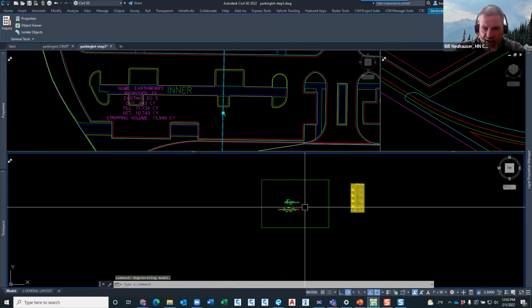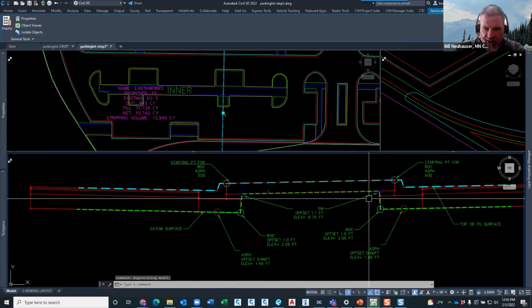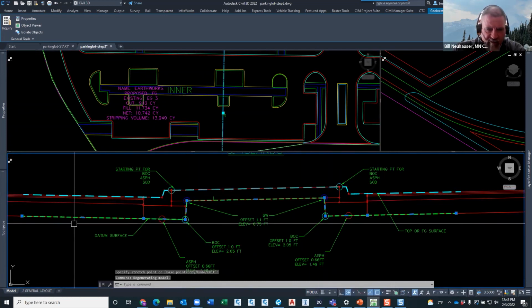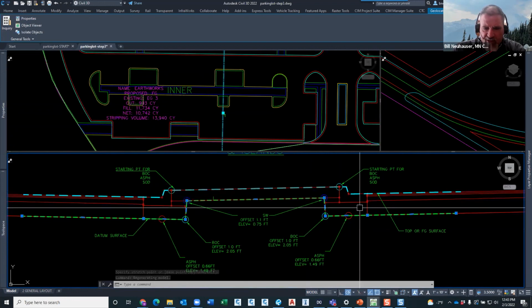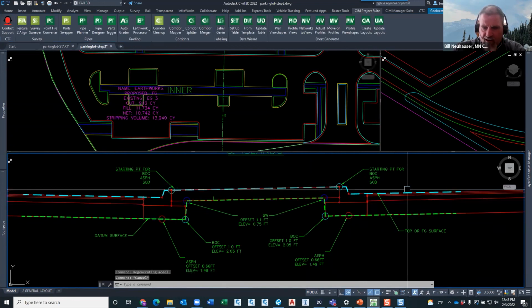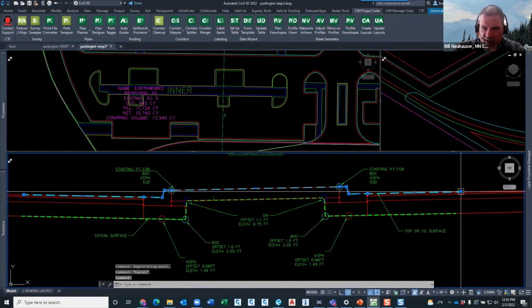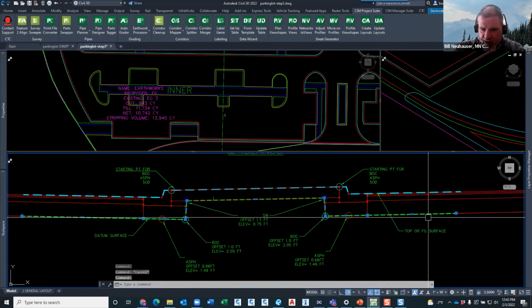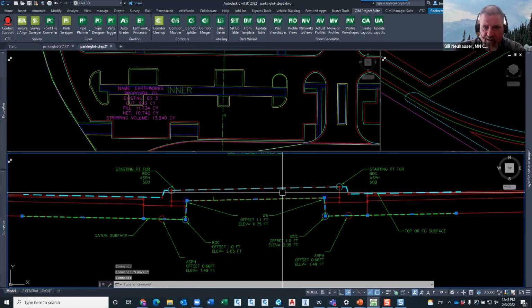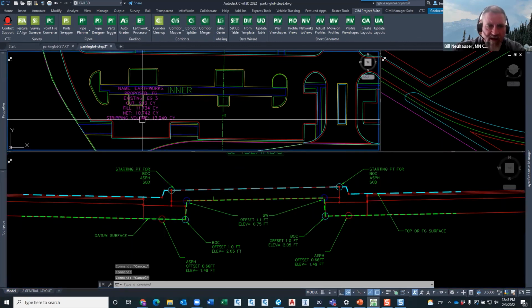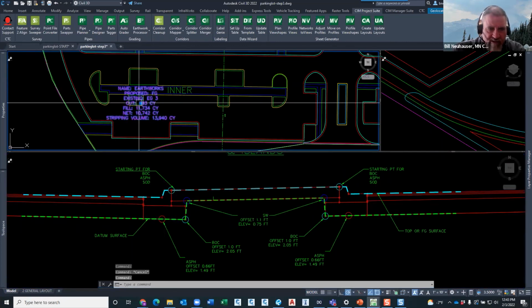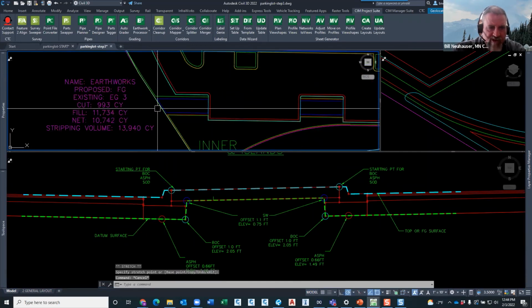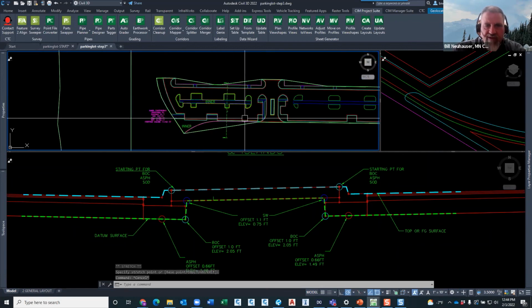And to kind of come back here and look at my sections here. Again, I'm trying to figure out how we can automate this process. That's the datum surface. That's what we're aiming for. Okay. You have this already. This has already been done. Feature lines, you know, etc. This baby down here, this is the fun one. Trying to come up with that surface. And here's the label that I talked about. It drops in here. Okay, proposed surface, existing surface, cut, fill, and the stripping volumes.